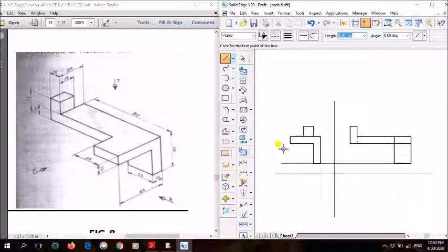Now, what are the surfaces which are not visible? Whatever this projection is, just concentrate on the left side of the screen, the cursor. This projection is fully a solid projection of height 25 and width 15. So height is 25, but we have only drawn how much? 15 mm. So what is the 10 mm? It is lying beyond, or behind, this solid, right? Hence this remaining 10 mm is not visible, so you need to draw it using dotted line. From there, just extend it downwards using dotted line. Same way again here, downwards using dotted line.